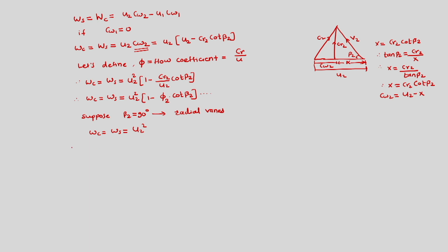So let us define one more term, which is pressure coefficient, or loading coefficient, as psi, and then this is WC upon U2 square.